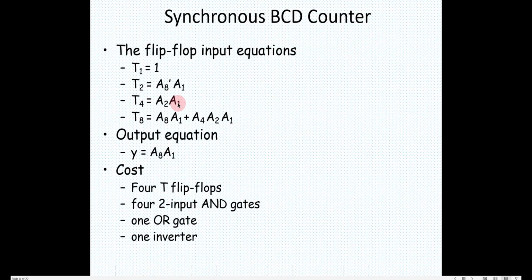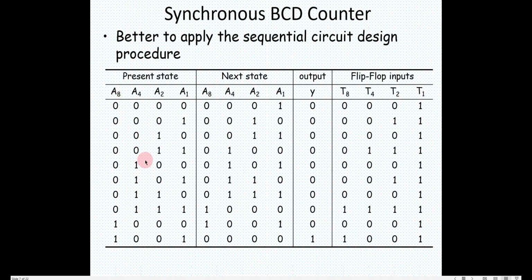Now what about the third one, the final one? If you see here, initially it was 0, it is making a toggle when all the three are 1. So that is one condition, and then again it is making a toggle when it is 0 0 1, out here from 0 0 1 2. If I use the condition 0 0 1, that is occurring here also, so it will toggle here also. So I can't use 0 0 1.